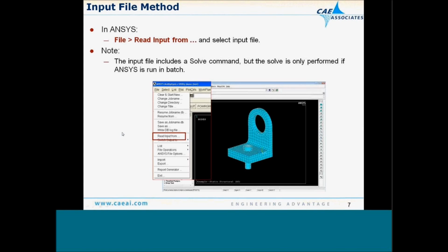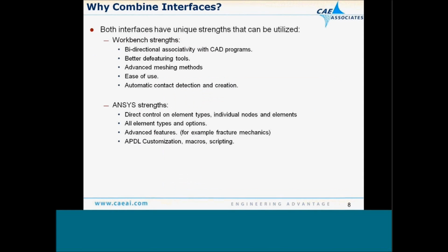And you could just as easily open up Classic ANSYS, choose File, Read Input From, and read that input file in, and then you'll have your entire model that was in Workbench in Classic ANSYS and see everything that's in there. So, you might ask, since we're going to be doing some things in Classic ANSYS with command blocks, why don't we just build a model in Classic ANSYS from the start and then stay in here and not have to worry about Workbench? That's certainly an option to you, but if you start off with Workbench, there's a lot